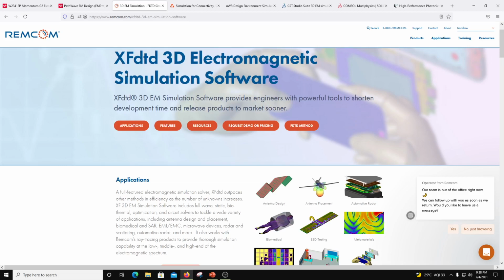Also, we are doing computation on half time steps. Okay, so that also is staggered for E and H, right? So by linear interpolation, you will be able to compute the E and H fields at any point. So that's what XFdtd is going to do.